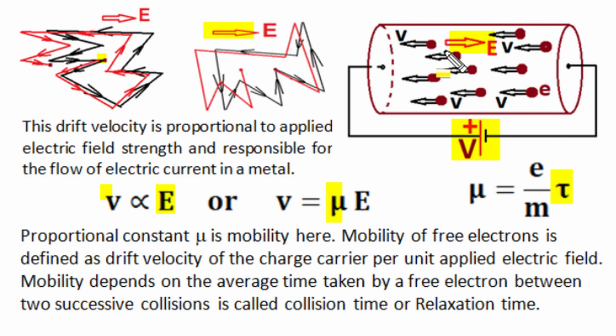If metal has higher purity and a refined structure, then during drift motion of these free electrons, fewer collisions will take place and there exists a higher value of relaxation time. The mobility of that material, having fewer collisions and a high average time between collisions, will be high, and that produces a higher drift velocity, so more charge will transfer, which indicates a higher value of conductivity.